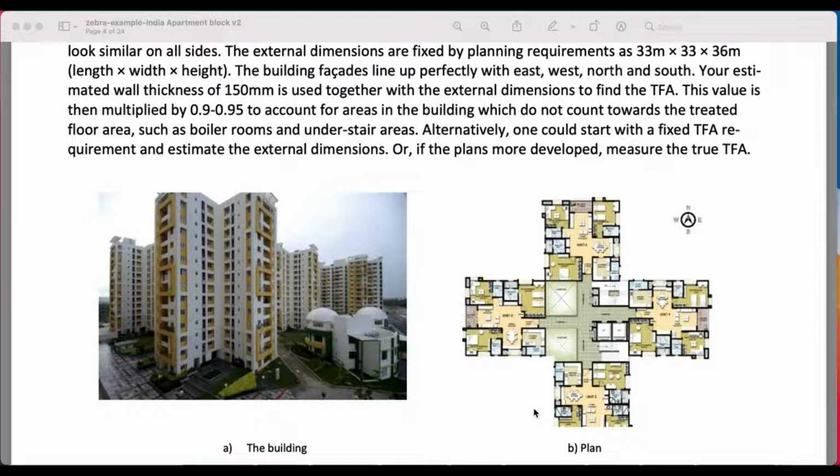And we're going to do that by considering the walls between the lobby and the accommodation blocks as either adiabatic, which means there's no heat transfer, and we're going to achieve that by setting their U value to 0. And we're then going to repeat the exercise, but with the U value of those walls set to the same as the external walls. And that will automatically link those lobby walls to the outside air temperature.